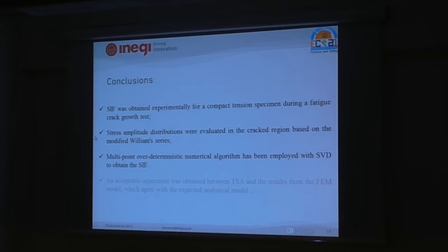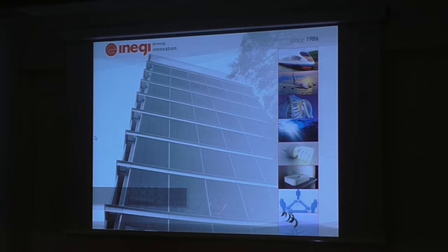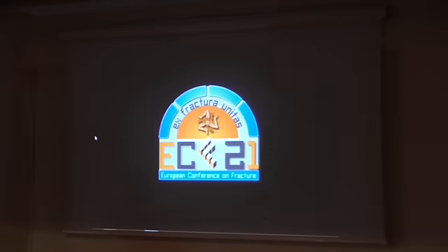So what we did was obtain the stress intensity factor experimentally with thermoelastic stress analysis through the modified Williams series and using a multi-point deterministic algorithm. And an acceptable agreement was obtained between that and the TSA.